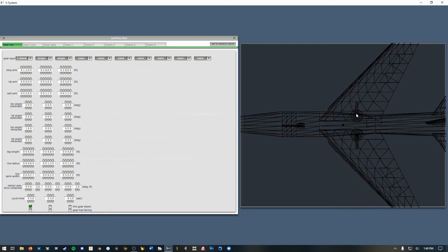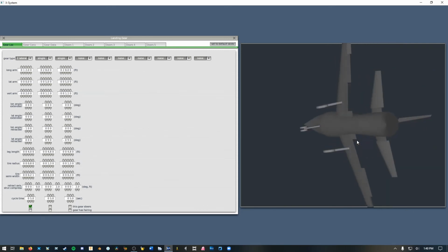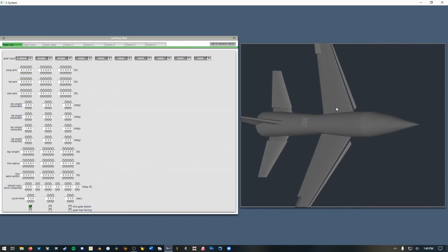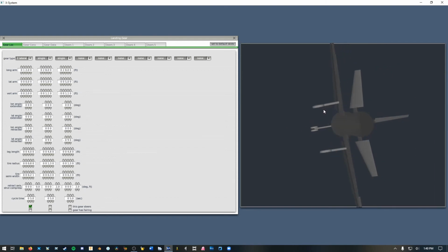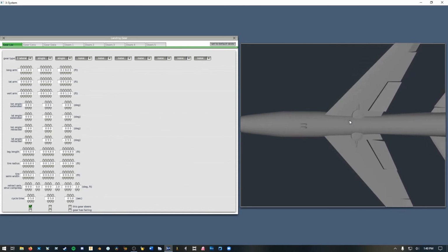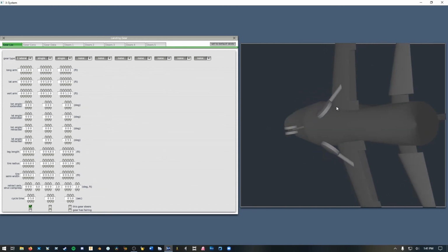But this is still not an optimal gear configuration for me, because part of my struts are hanging out of the aircraft. This will create drag. Now you can get around this by making your gear skinnier, but skinnier gear are less grippy and less stable, so you'll skid around a lot more when you are trying to move at high speed on the ground.